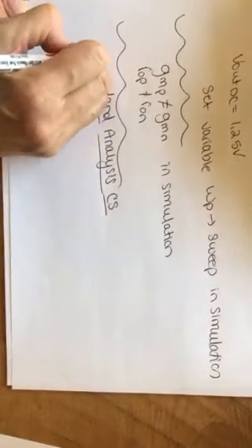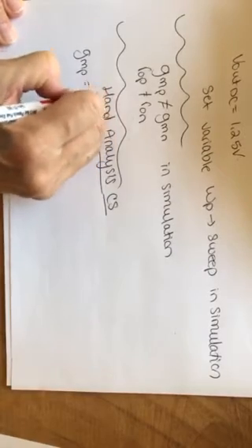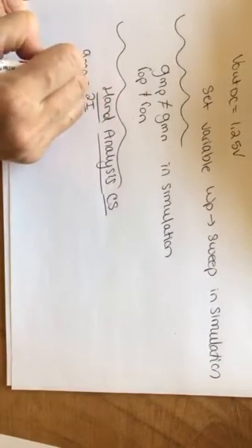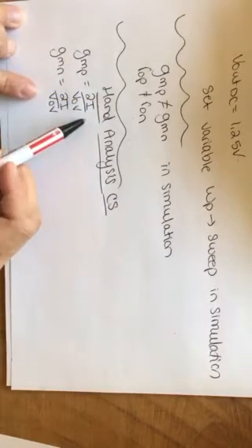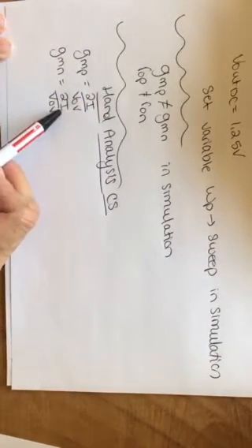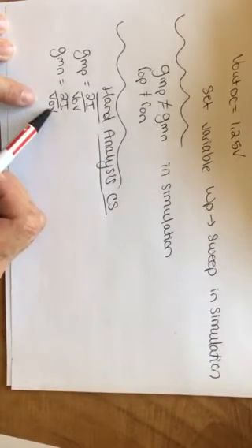So you must hand calculate gm. The gm of the PMOS is 2I over VOV, and the gm of your NMOS is 2I over VOV. So again, this is showing you that if you picked your VOVs to be equal between the two, your gms would be equal, but when you're in simulation, those will probably be slightly different.